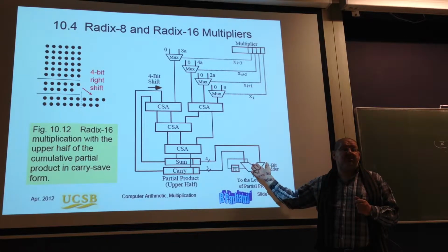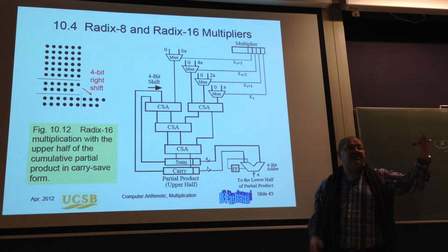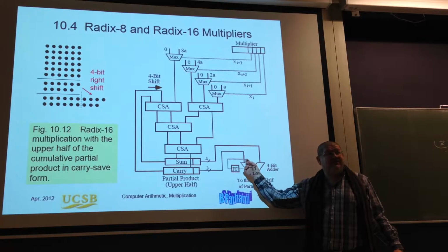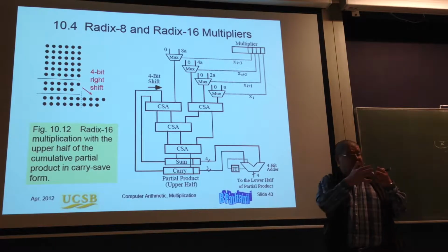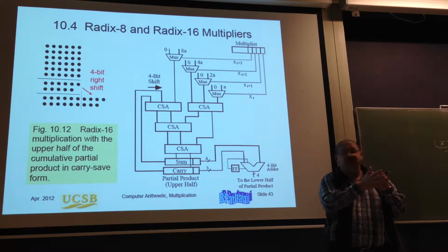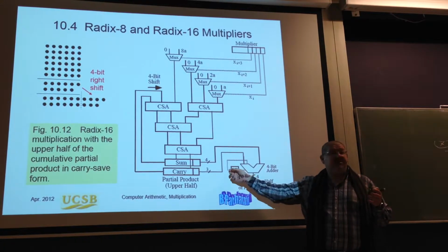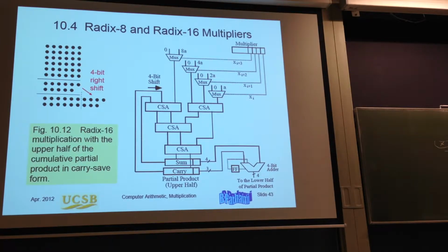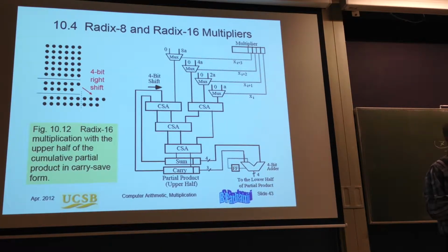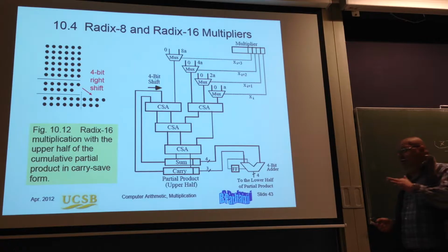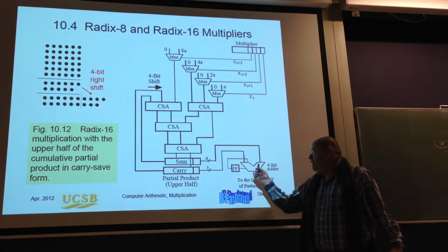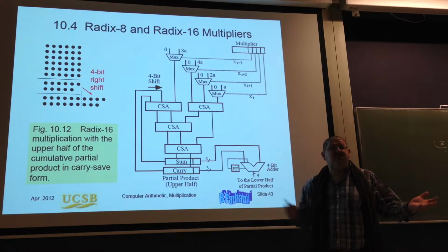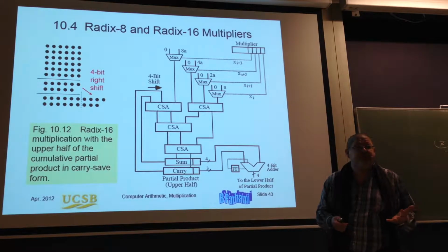build a lookup table. Then I have the inputs. There are 4 bits, and I have a lookup table. I use those bits as address, and from the lookup table, I read the result and I read the carry, right? It's getting larger, but it's still doable. Depending on the technology, I may rely on that or not. Most likely, if I try to build another adder which is fast, it won't really help a lot.